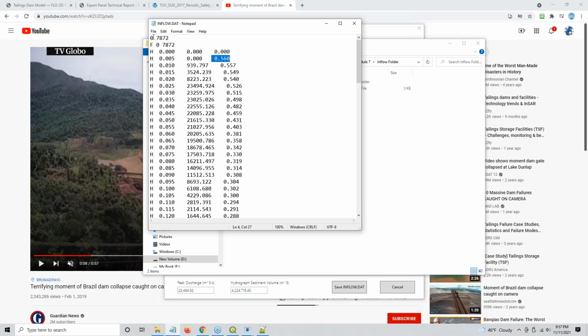Okay, and so this 0 means that it's an hourly simulation, not a daily simulation. This is the grid element that you see when you run this scenario in graphics mode. This will be the plot, the one that chooses to plot it. We only have one here, so you don't see anything else. F means floodplain, 0 means inflow, not diversion, and this is the cell we set it to.